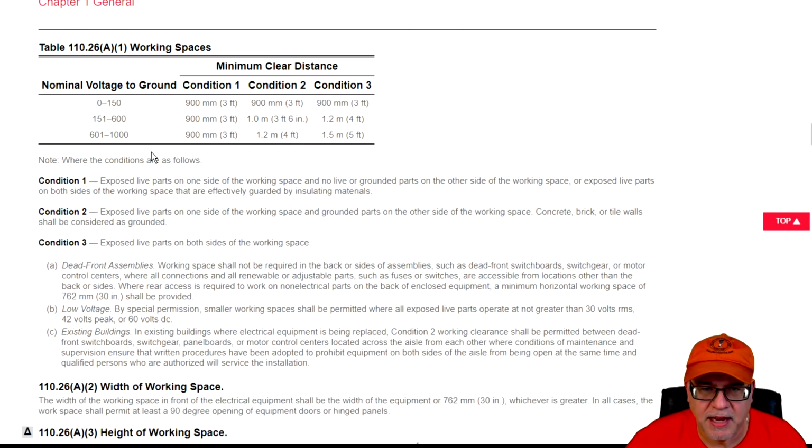So if you look at this table here, if I see a 120 volt application, it's 120 to ground, okay? It's not the 240. I see a lot of students do that on exams and get confused. We're talking about the value to ground. 240 is from line to line, okay? 480 is line to line. But if it's 277/480, it would be 277 to ground. You with me?